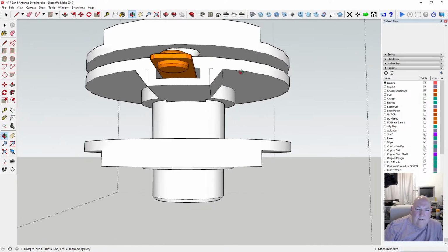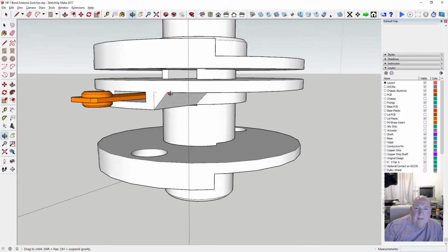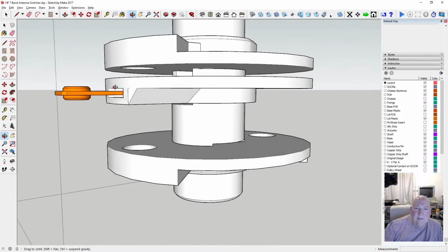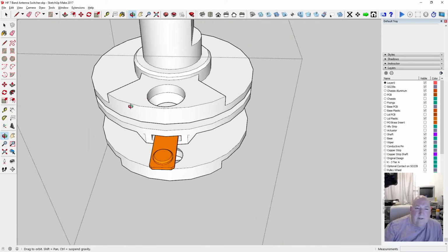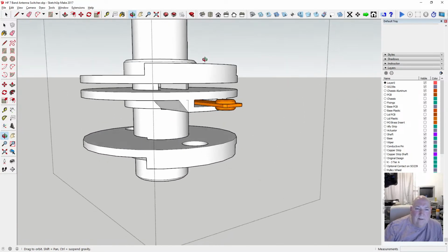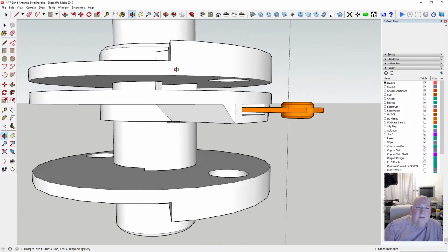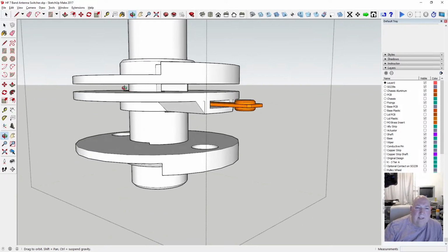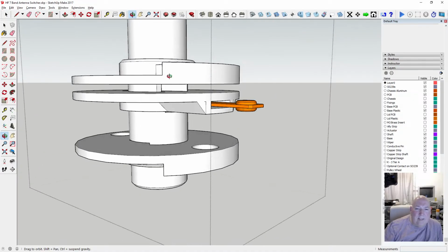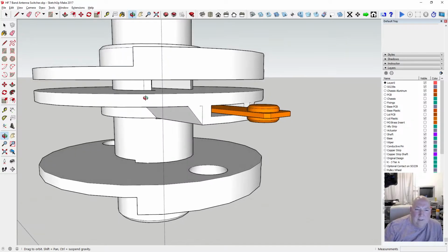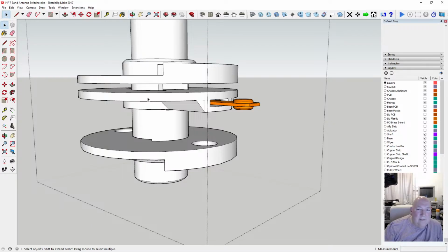So that'll automatically sit on that next one. I suppose we could make the top one thicker. No, it's got to take the ball bearing, isn't it? No, that's got to stay where it is. So that gets printed flat as well. So we want a little spacer printed out in there, similar to that collar size. Or we just go ahead and make this one thicker. I think we'll just do that, it's simpler. Yeah, we'll just make that one thicker.